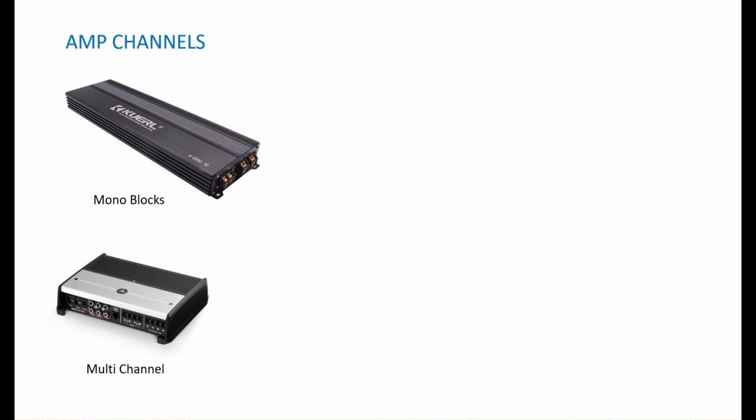But amplifiers also come in multiple channel formats, with 2 channels, 4 channels, 6, 8, they're all common formats. Multiple channel amps are like having 3 or 4 little amplifiers all in one unit, right? So that you can control multiple speakers or multiple speaker pairs. Each channel can control one speaker and has a negative and a positive output. So if you want to drive 4 speakers, you need a 4-channel amplifier.